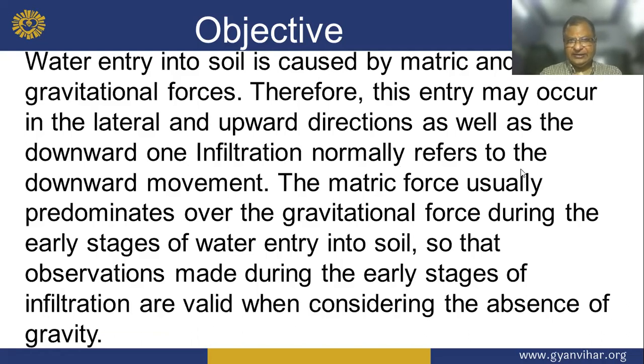Water entry into soil is caused by the matric and gravitational forces. Therefore, this entry may occur in the lateral and upward directions as well as downward, and infiltration normally refers to downward movement.